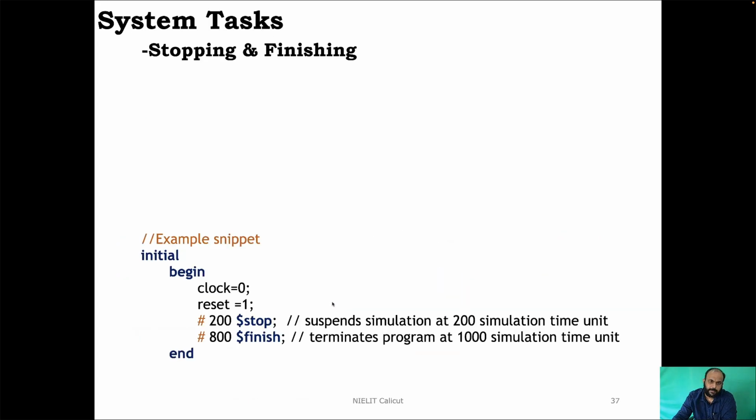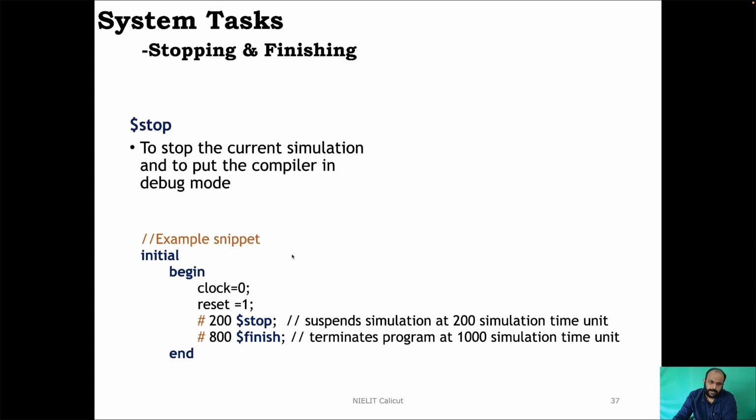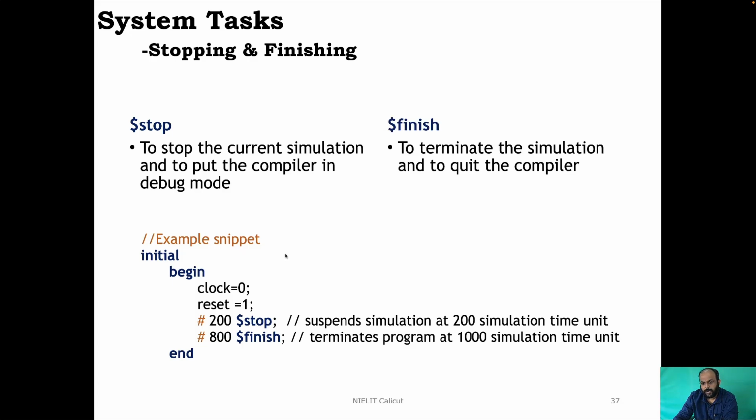Now let's see the system tasks for stopping and finishing the simulation. $stop is a system task which stops the current simulation and puts the compiler in debug mode. Similarly, $finish is also used for stopping the simulation, not only stopping but also terminating the simulation and quitting the compiler.